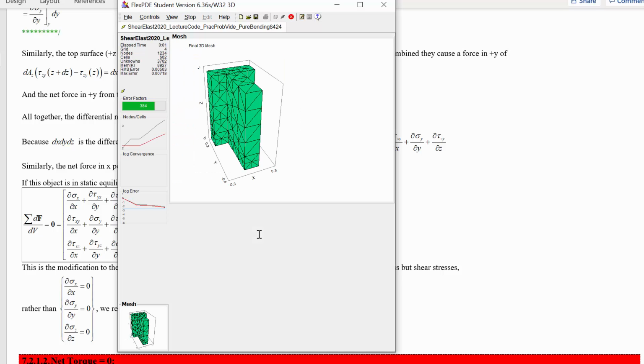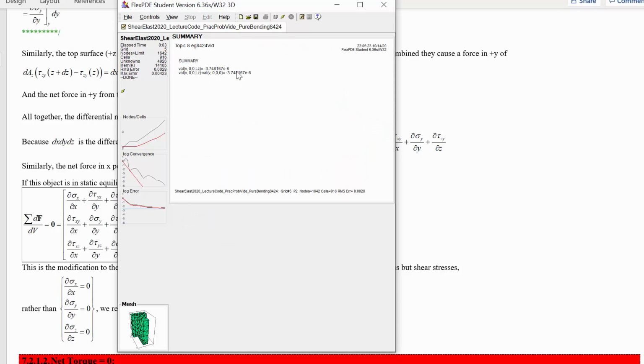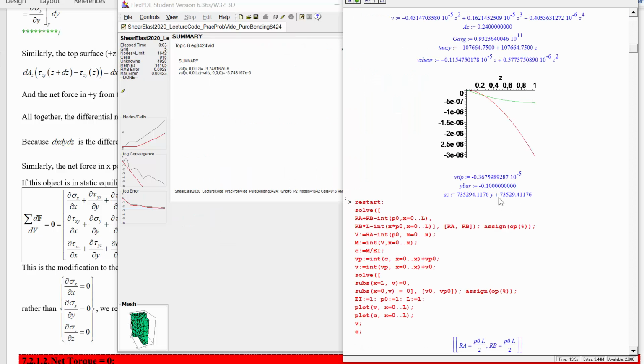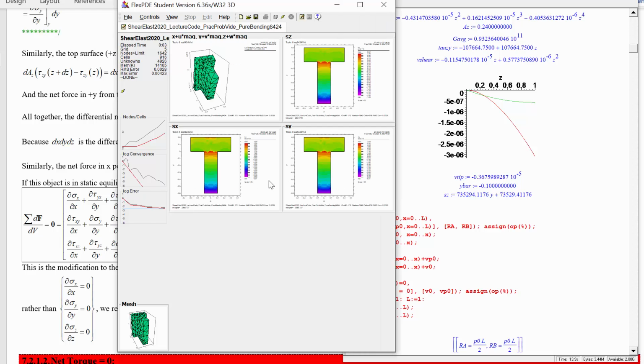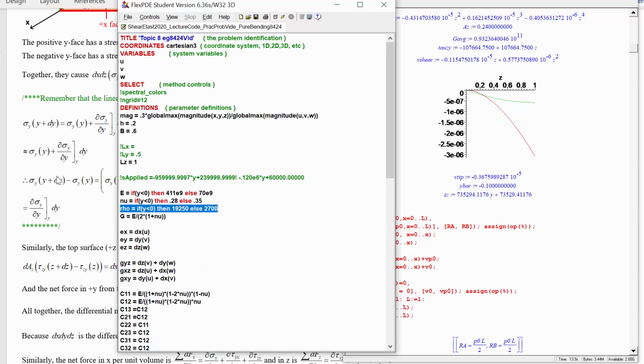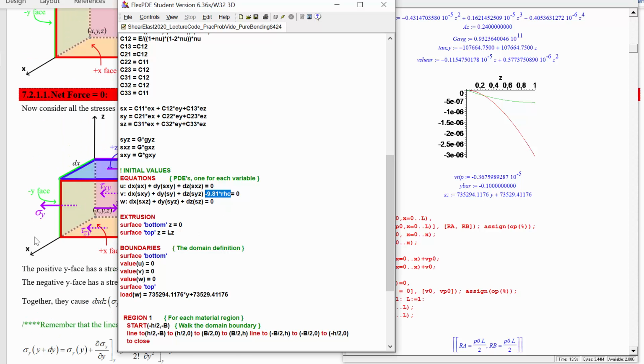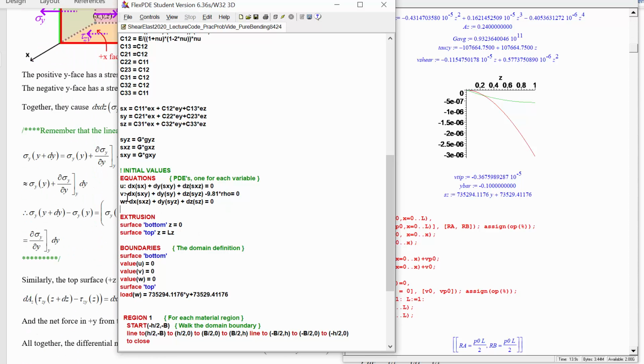This now should incorporate the weight of this thing and give us closer to what we had in Maple when we have gravity applied. So that's all you have to do. Once you've put in what the density is, by remembering where the differential equations in FlexPDE came from, and not just this magic thing that you don't change anymore, you could actually go and mess with them a bit if you're feeling brave and willing to remember where these proofs came from,